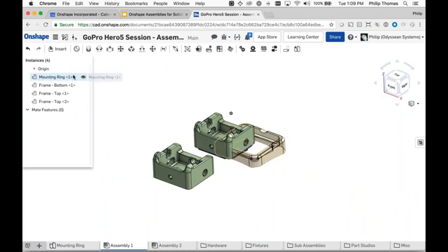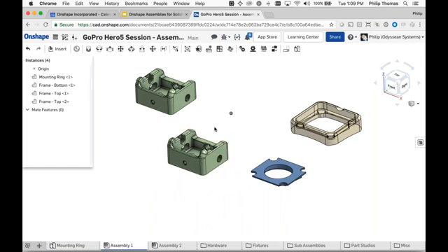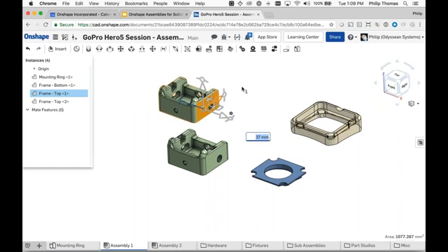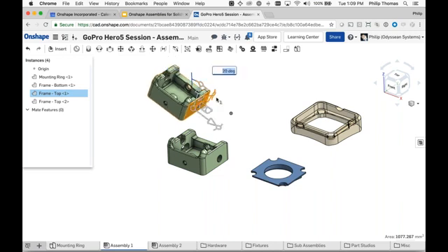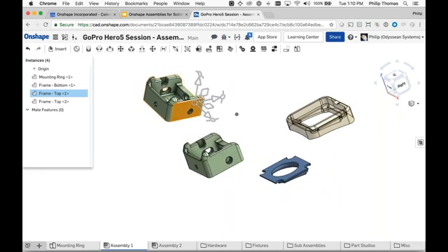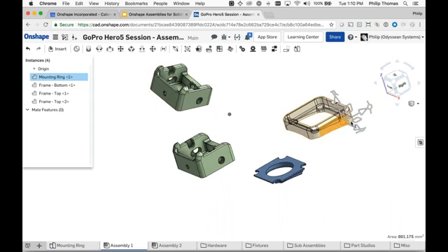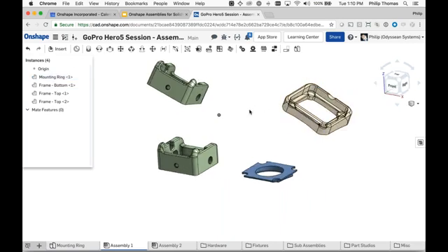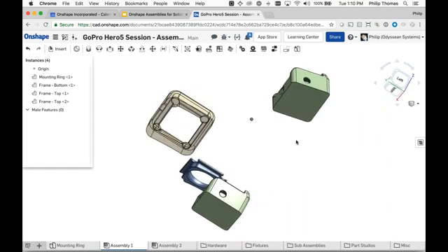Dropping components in the assembly, unlike SolidWorks, did not fix the first component. Each and every component has 6 degrees of freedom, and I'm free to pick up any of these and move them around. And I'm now going to introduce a new concept, the Onshape manipulator. Selecting any part by clicking on it brings up the manipulator dialog, and it's fairly easy to determine how this works. You have the linear modifiers, I have rotational modifiers, and I have planar modifiers. In this particular case, these squares mean a linear motion in 2 of the planes. And all of these parts are free to float in space. If I would like to position any particular component on the origin of the assembly, it's very easy.